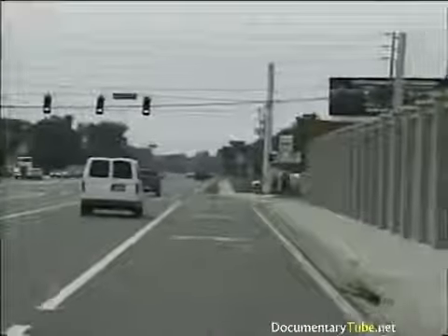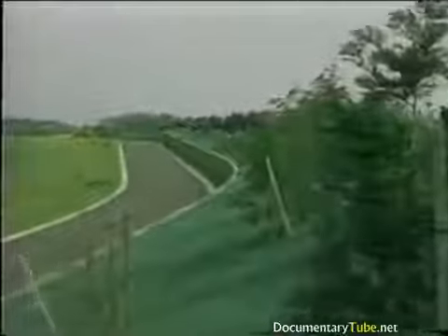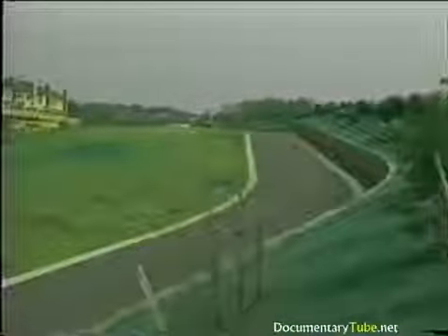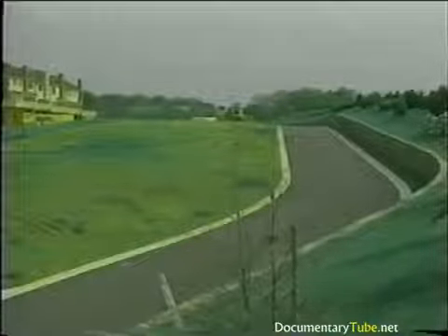The amount of attenuation provided by these objects depends on the size of the object and frequency content of the associated noise source. The term noise barrier refers to any large object that blocks the line of sight between source and receiver, including the ground itself if it protrudes upward through the line of sight. A noise barrier is commonly a wall or earth berm specifically constructed for the purpose of noise reduction. This type of obstruction is the most commonly used traffic noise abatement measure.